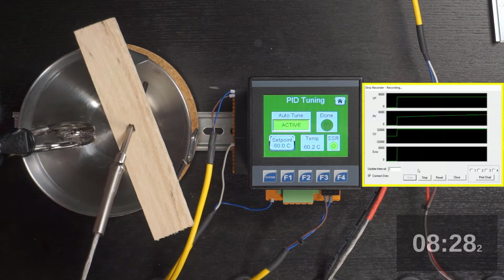Now during auto tuning, you have to get above the set point by a little bit before it actually turns off. So you can see in this case, after 0.3 degrees C, based on the scaling, we turned off the SSR. And so even though the temperature continues to creep up because of inertia, we are now headed down on the first cycle. So we're going to need to go below the set point by a similar amount that we went above it before this cycle will be complete.